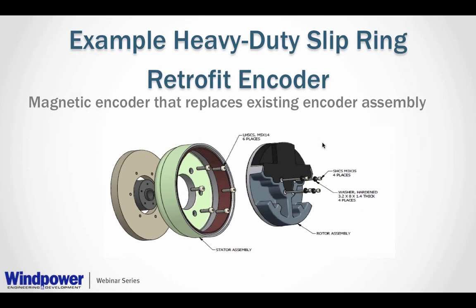Instead, what you can do is use a simple magnetic encoder, for example, this model, and you can see this has got some really simple construction mechanically. It's got a ring on the outside, and then it's got the electronics in a potted brick in the center. This gives you some real incredible durability because now you're not using encoder bearings, you're not using couplings. It's directly mounted on the shaft assembly, and it's all potted in plastic, so it's really, really resistant to temperature. It ignores oil, water, and grease.